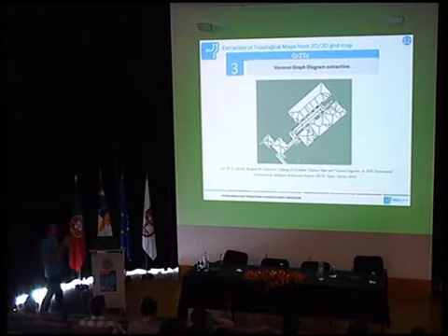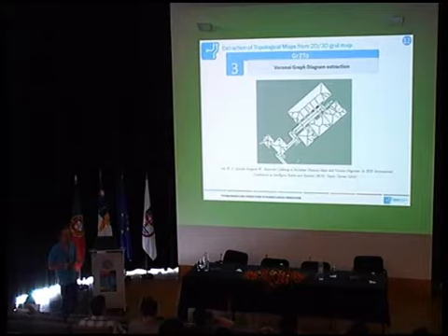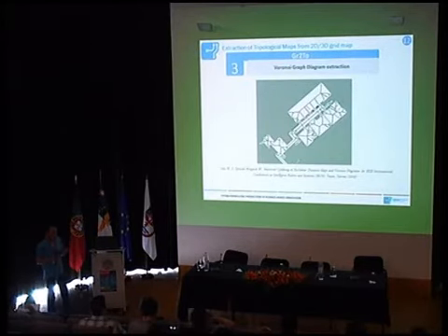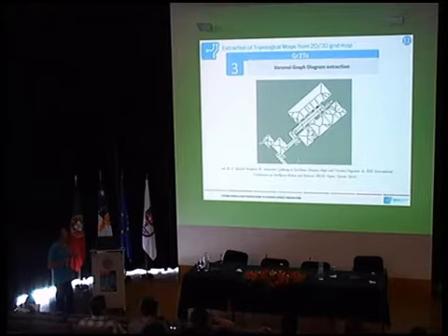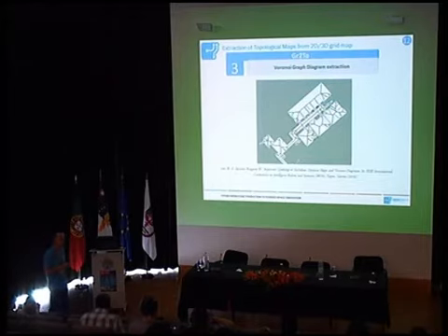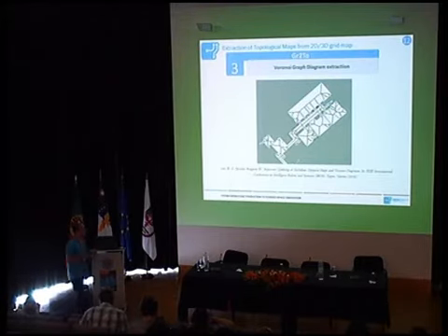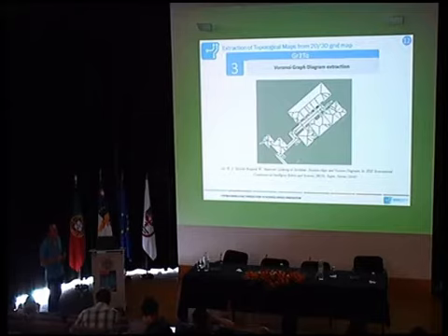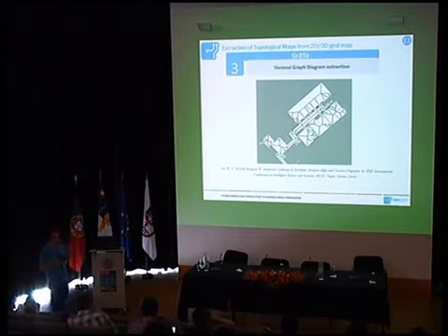Then we extract the Voronoi graph. What is a Voronoi graph? A Voronoi graph is composed of a set of edges. These edges are defined, in the distance map, by the cells that have at least 2 occupied cells at the same distance.